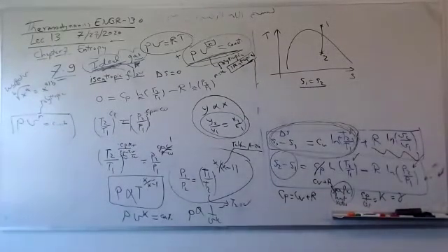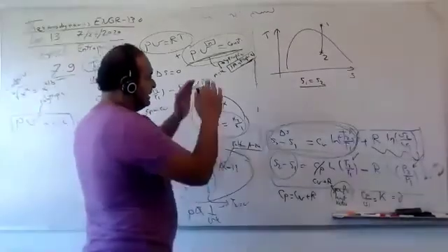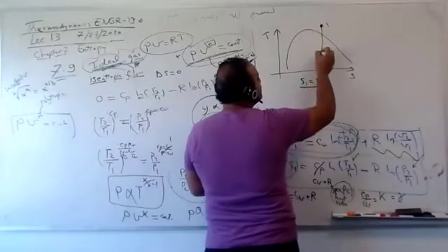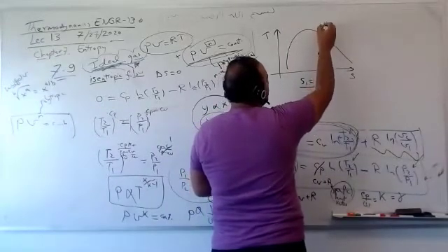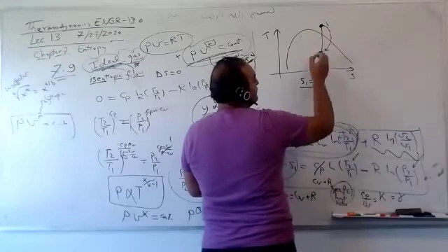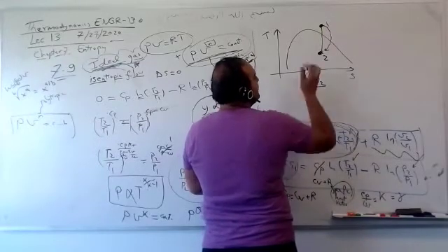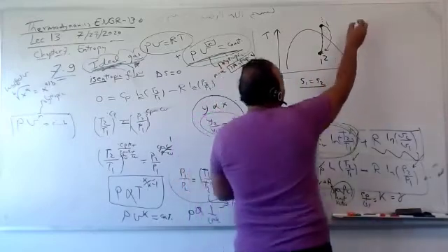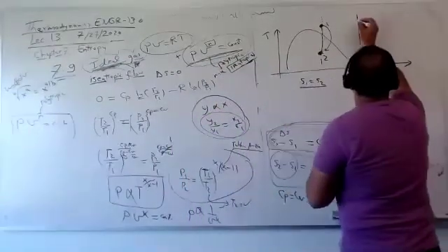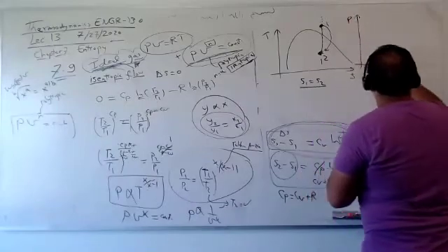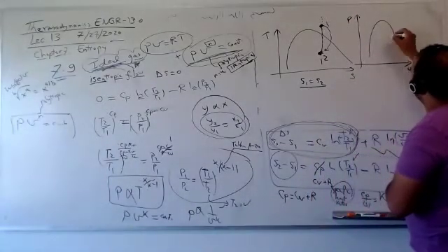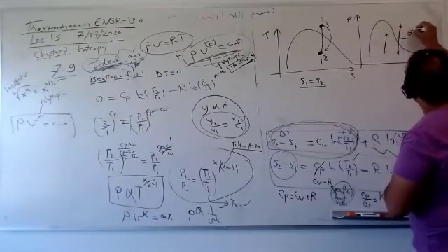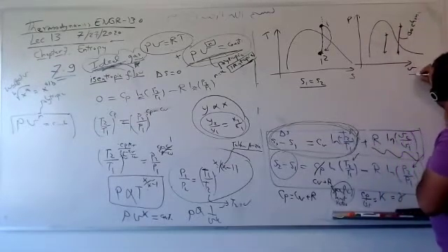If I said in a problem using steam table, the second category, if we have this process isentropic, you can obtain S1, for example, from point 1, give it to point 2, state 2. It means you move vertically in TS diagram. If I told you you have a rigid tank, let's say this is a PV diagram, it means you move vertically, let's say from here to here. This is called isochoric, constant volume, correct?